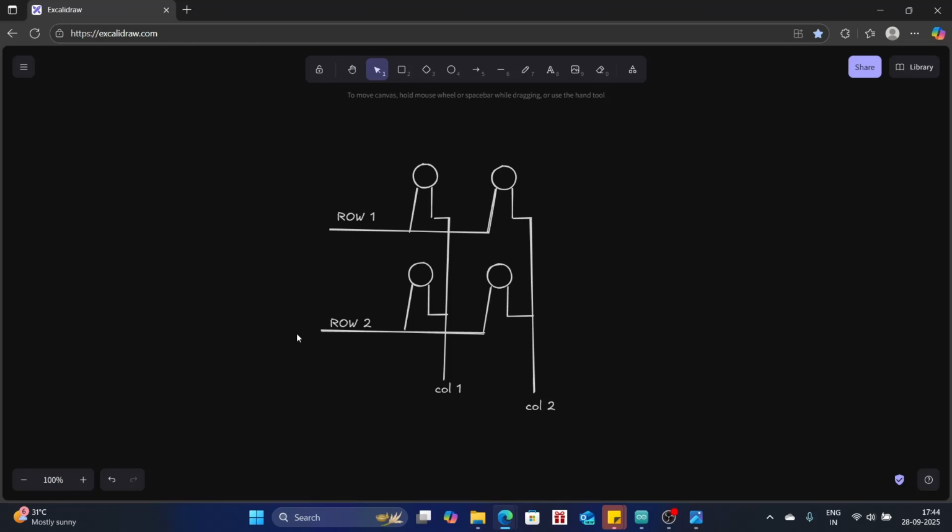Here we're going to set the signal to low, and here we're going to set the signal to high using the 4 Arduino pins. So this LED is going to light up, and after that we're going to set this column low, and then set this column high, and then set this column high and this one low. Then this LED would light up.